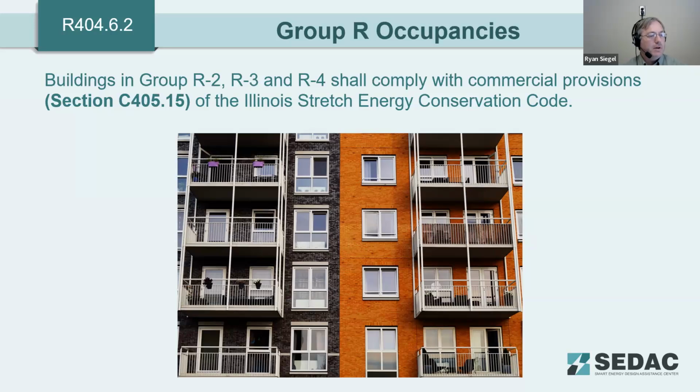What we're seeing for most homes, 200 amp service is oftentimes feasible, even with the electric heat pumps, the supplemental heating, not the backup heating, but supplemental heating that they may require, all the heating appliances, understanding that there is a lot of diversity in all electric homes out there for that.